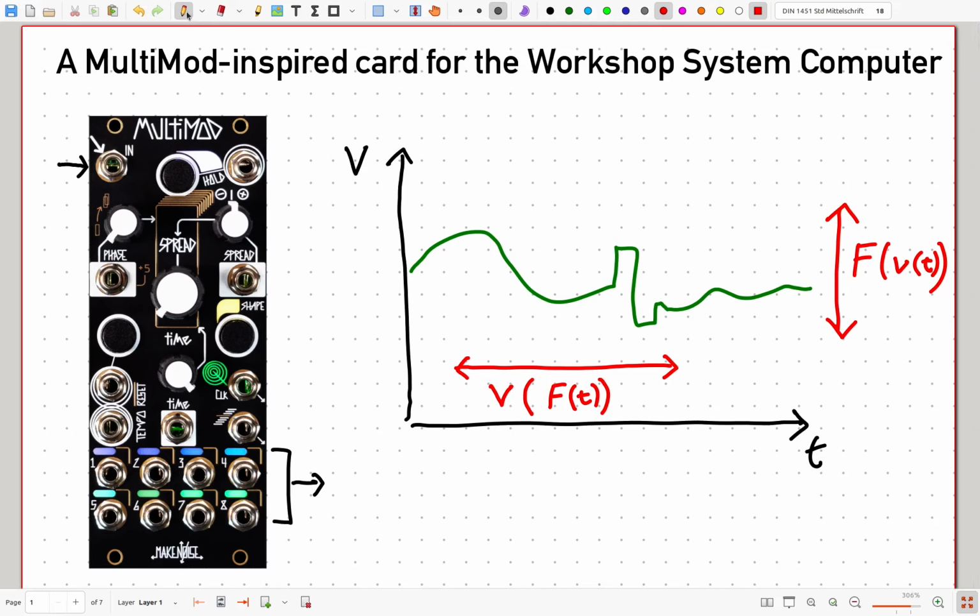And what that means is that most CV manipulation tools, because they affect that voltage, have a different effect on all of those signals. So for example, if we multiply a volt per octave pitch signal by a factor of 2, then we completely scale that and make it go out of tune, or we change the set of notes that it represents. Whereas if we scale a set of gates by a factor of 2, the voltage is there. It makes no difference at all. If we do that with a volume CV, it makes it louder. So the same manipulation of that CV has a very different effect depending on what type of signal is going into it.